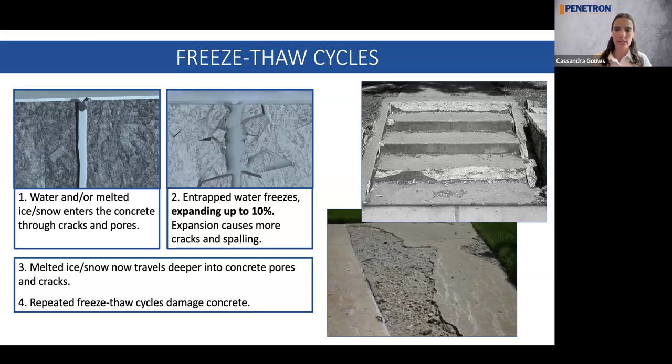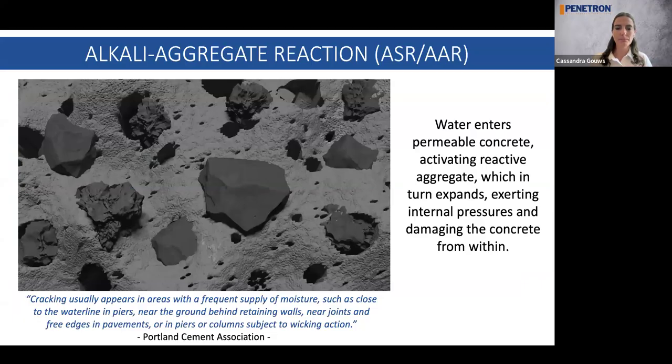You can very clearly see in the top right photo with those stairs, pieces of concrete actually break apart. Very interesting. A 1 millimeter size crack will actually double in size in as little as 8 freeze-thaw cycles, and that can easily happen in a week or two. So the damage happens much faster than one could think.